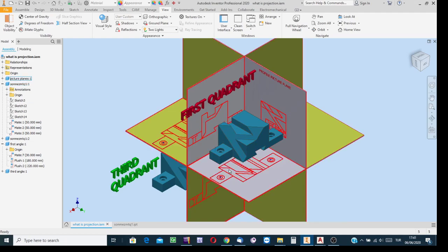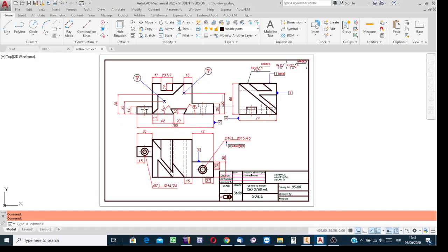Since the adjacent views use the same coordinate axis, mathematically speaking, it is obvious that the front and the top are related views. Top and the left side or right side are related views. Front and the left or right side are related views. These are dependent on each other because they use the same coordinate axis. But in engineering drawing, to be able to have the views consistent with each other, at the background, at the view construction stage, we have lots of transfer lines.